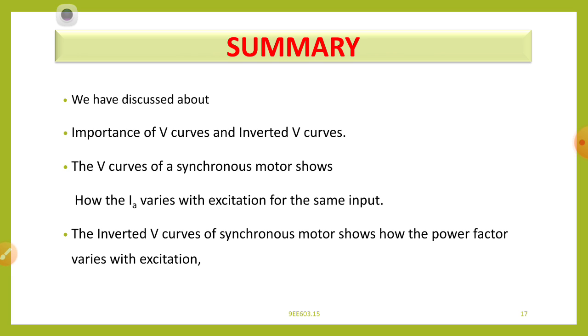They draw lagging power factor, which means they consume reactive power, whereas our synchronous motor generates reactive power, measured in kVA. Reactive power is generated by the synchronous motor and consumed by induction motors and transformers.